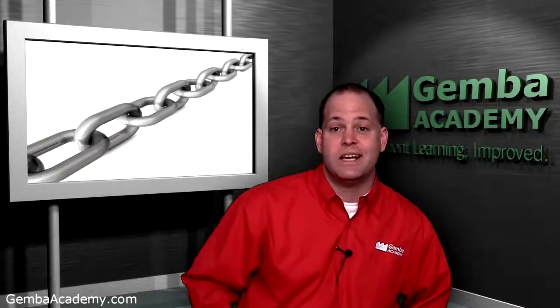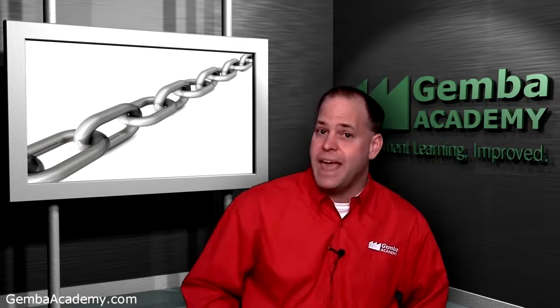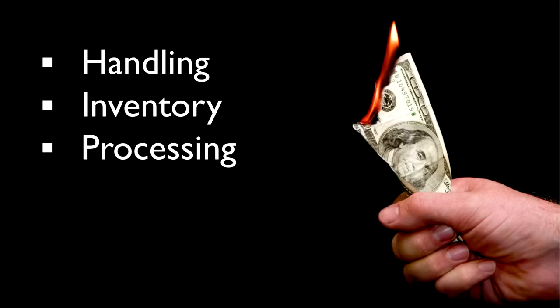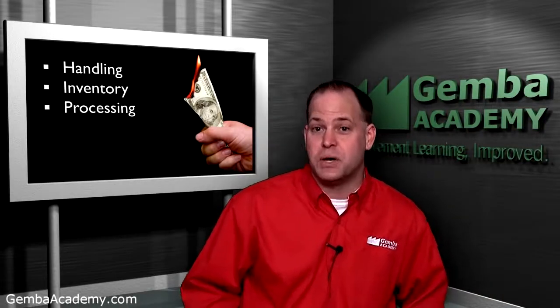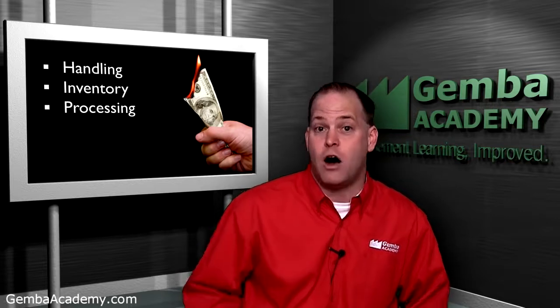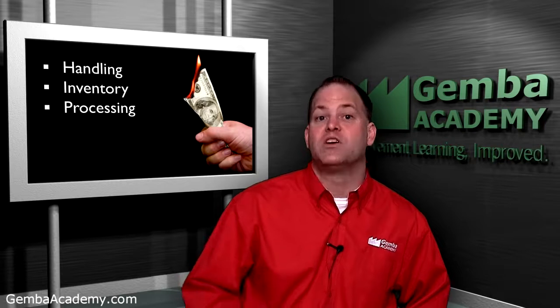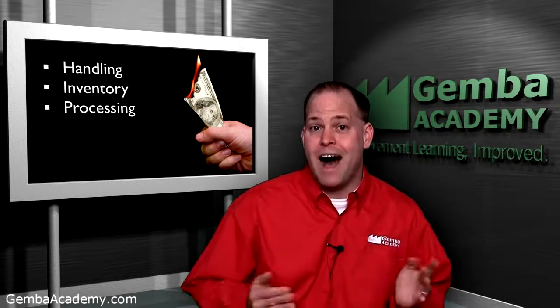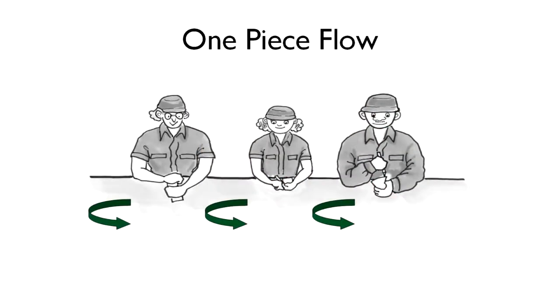Now, with this said, Kanban systems are far from perfect. You see, the Kanban system can be full of waste, such as excessive handling, inventory, and processing. In fact, the ideal just-in-time production system would use no Kanban at all, so long as it produces what the customer wants, when they want it, in the quantity they want. In other words, our goal shouldn't be to implement a Kanban system. Instead, our goal should be true one-piece flow.